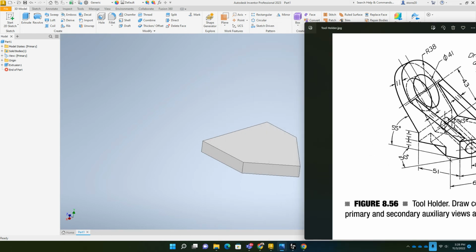Once I'm done with that one, on this surface right here, I would create a sketch. Once this part is done, once you have this little round feature right in here, I would create a sketch on this surface here to then sketch a triangle, or actually just a line from here to here for this line here, and then simply extrude it to get that part right in here, extrude 11 millimeters. I would do the same thing on this back surface over here. I would create that sketch so you can do this line and extrude it 11 millimeters.